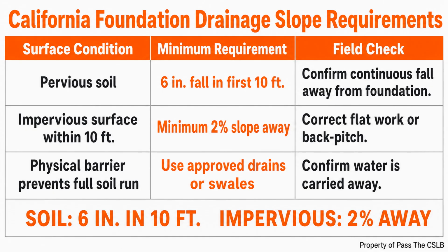Confirm the surveyor's control, identify monuments that need protection, pre-mark the excavation in white, complete the notification process, designate the competent person, establish working layout outside the dig area, verify finished floor and drainage elevations, then brief the operators and foremen on the control that cannot be disturbed. I want to close the technical part with one field checklist you can remember without carrying a textbook.